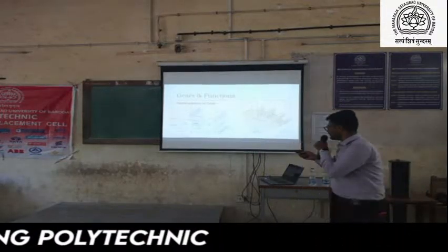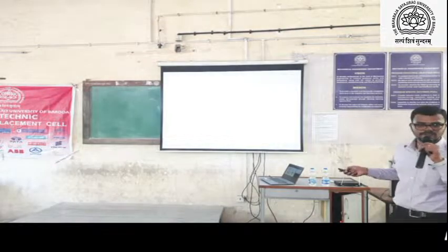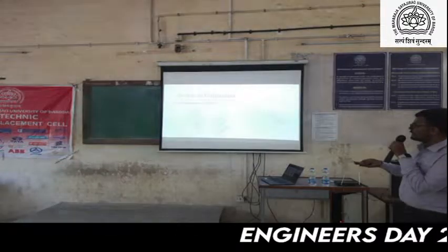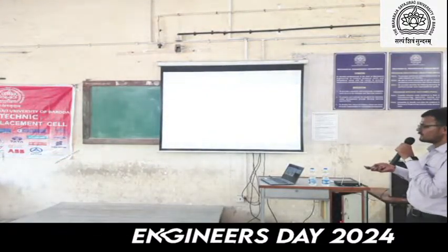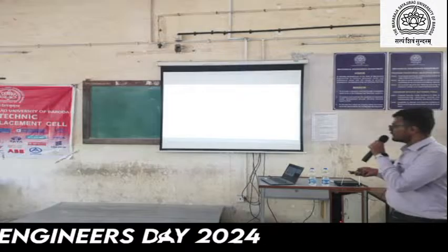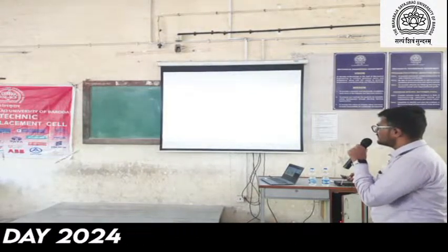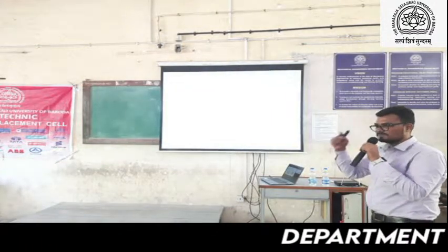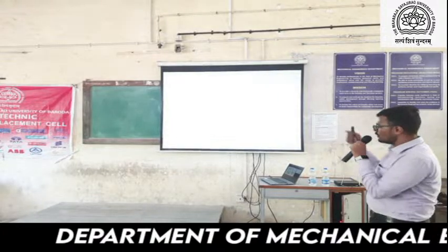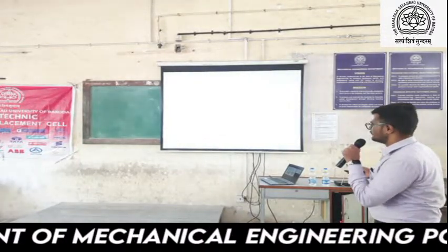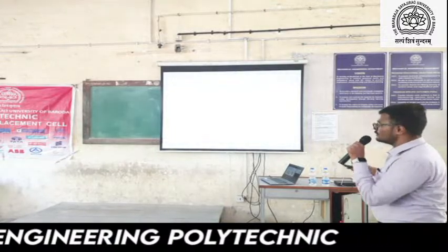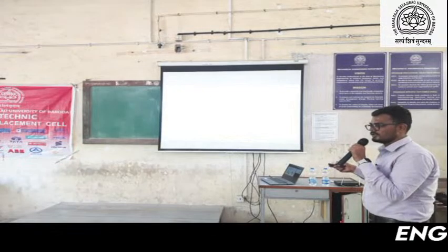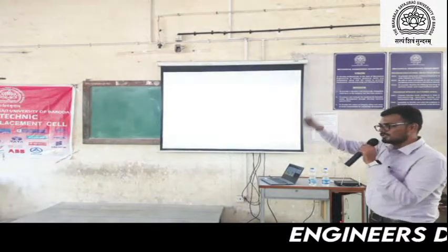Exactly. Actually, this nomenclature is the heart of gears. So you can't hesitate or avoid anything about this nomenclature. See what is it? Top line. This is the pitch circle diameter we used to say. So below, this is dedendum, this is addendum. Addendum and dedendum will be segregated with this pitch line. The space which is above the pitch line is addendum, and the space which is below the pitch line will be considered as dedendum. So these are all the gear nomenclature. Wherever you are studying about gears, you need to correlate with this nomenclature. That's why even in academics this will be in the syllabus.